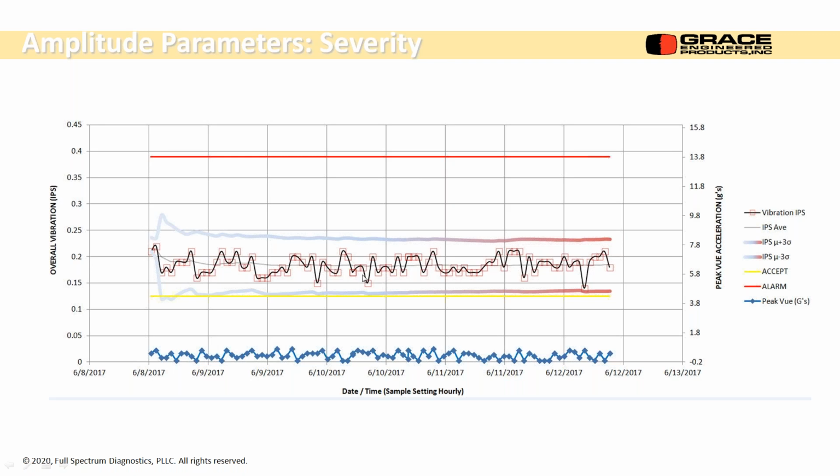So they're going to have better capability in the transducers they currently have. They're going to be able to monitor the X, Y, and Z low frequency range. Plus, they can do some sampling and bandwidth filtering to be able to get the really high frequency usefulness out of them. So 5 kilohertz up to 8 kilohertz or whatever the limit is on these. So that's a nice development.